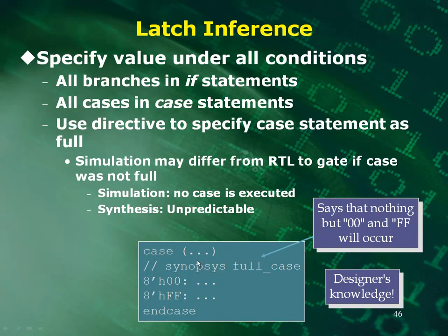Just be sure that you specify the value under all conditions. So that would be all the branches in the if statements, all the cases in the case statements, and use a directive to specify the case statement as full if you need to. You can also put a default statement in. I didn't put that here. I should have done that. You could put your default statement in and make sure it gets a particular value. And just keep in mind that the simulation may differ from RTL to gate if the case was not a full case statement.